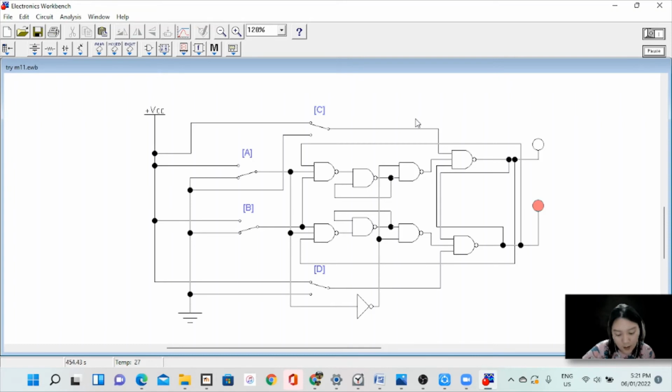And if the clock is 0 or is connected to the ground and our toggle is at high, it is still on hold. So no matter if we switch the value of our T from 0 to 1, the output would still be on hold because the clock is set to 0.